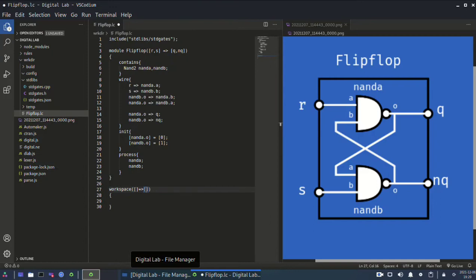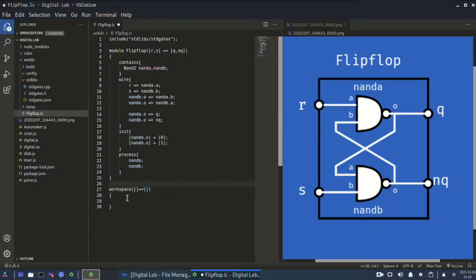And here also you have to define the inputs and outputs. If you don't have any input, you can just put it like this. It is necessary to put the square brackets. If you don't have anything, just put empty square brackets. Okay, then we will have A comma B here, 2 inputs A and B, and outputs maybe C and D. Okay, C comma D.